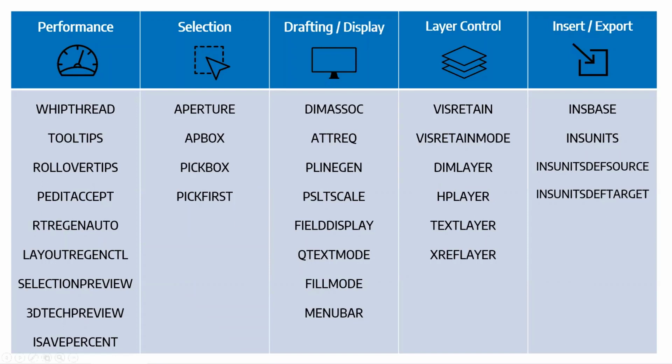So look, we did have one question pop up towards the end here, which was, and I'm literally reading it as I've seen it, will the INSUNITS command set the standard units for the entire drawing? For example, I set INSUNITS to millimeters and draw a line. That line will be in millimeters, correct? Okay, so I suppose you're drawing at 1-to-1. So this is more about bringing content in. Yeah, if you're drawing in millimeters, you set your insertion units as millimeters. So if you're drawing in meters, set it as meters. Exactly. So hopefully that answers that question.